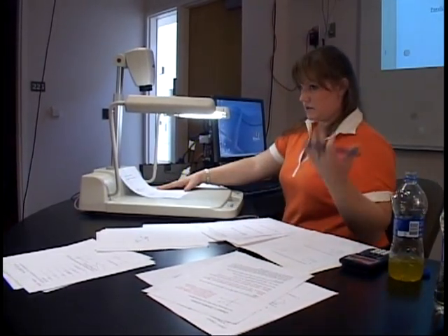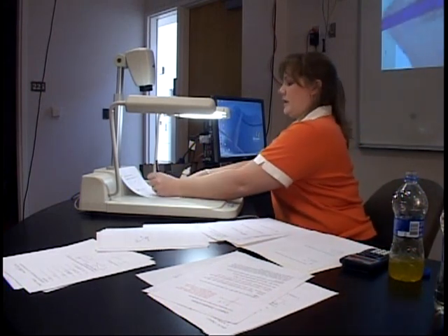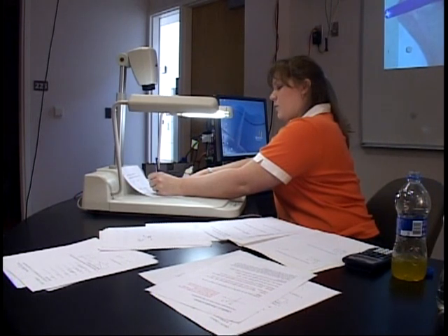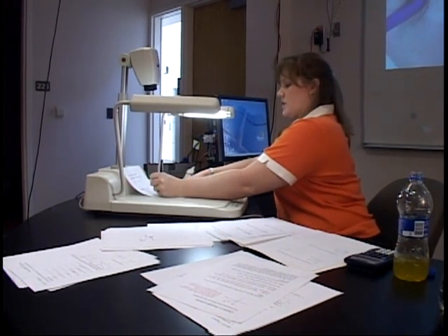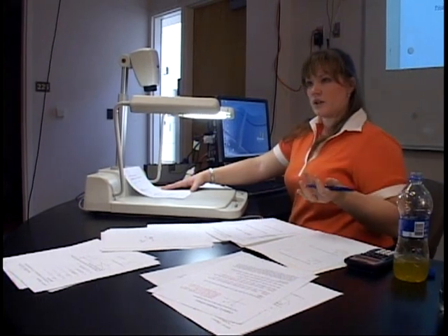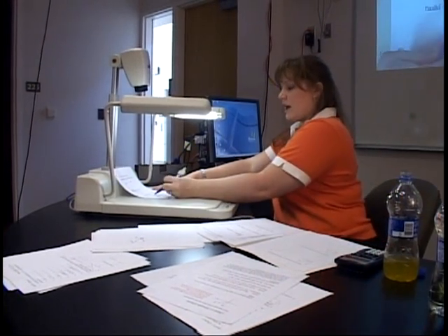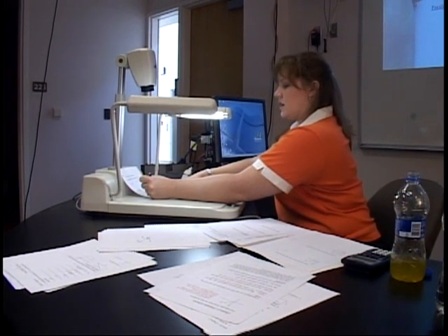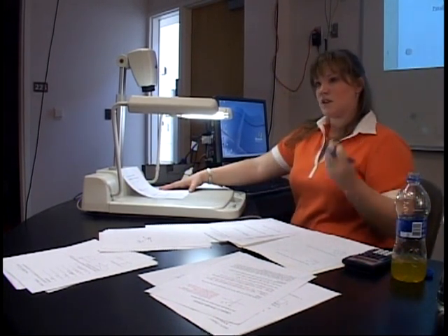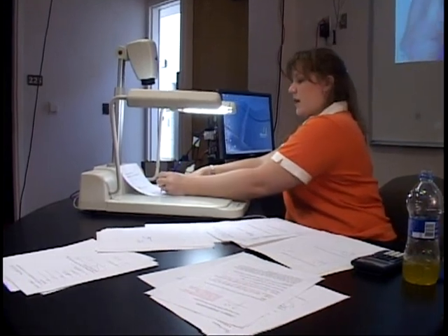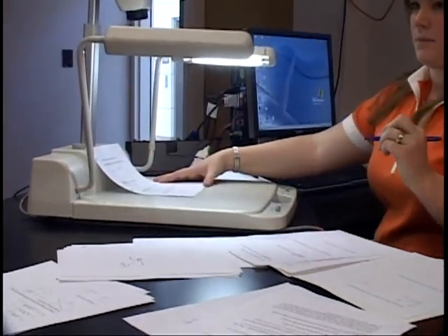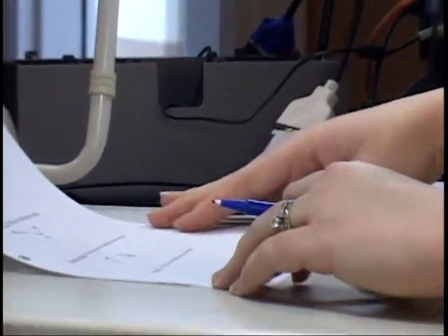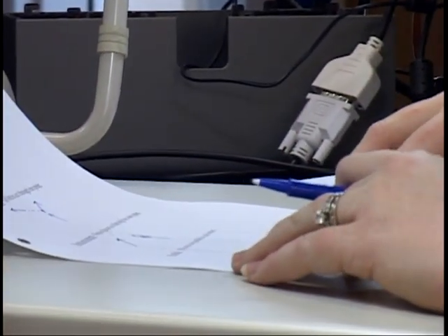Non-concurrent means just that they don't act at the same place, right? So you may have one over here, and if we're talking about this point, and you have another force over here, those are non-concurrent because at the point that you're looking at, they don't happen at the same place. Now, if you follow these along their lines of action, there may be a point out there in space somewhere where they cross, but if we're talking about this point, they're non-concurrent. That also will come into play very quickly whenever we learn about moments.